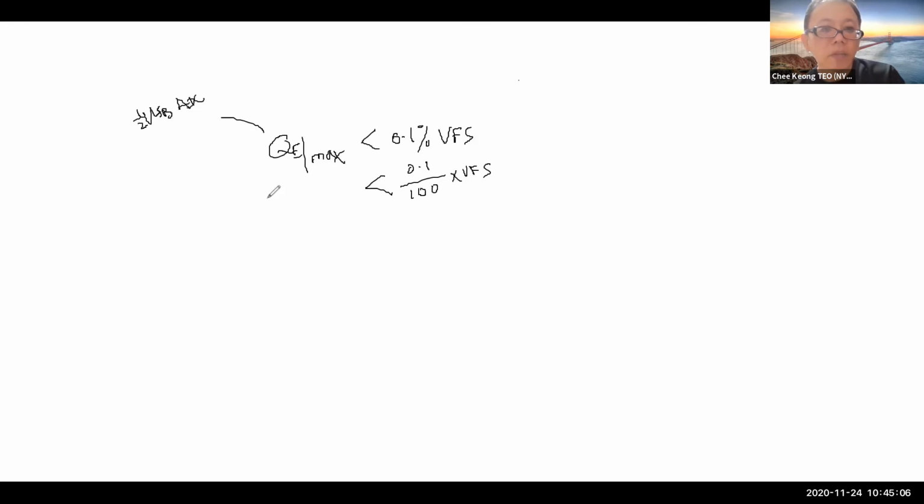And we know that VLSB for an ADC is given by V full scale divided by 2^n minus 1. 2^n minus 1 is your interval. This is your VLSB, right? But the maximum quantization error for half VLSB is 0.5 of that. So you have to multiply 0.5 by this whole thing. Sorry, let me erase this part, it's not so clear.